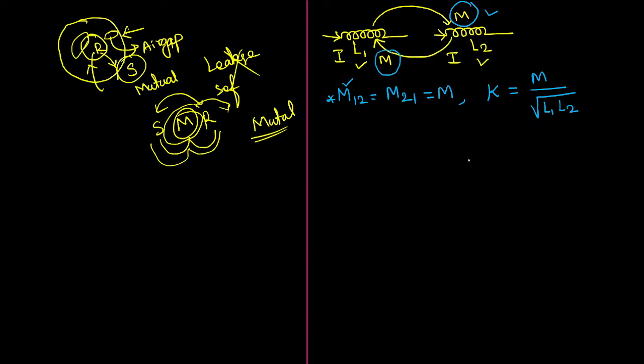The derivation is there; you might have gone through it in the lecture. This is in terms of electrical inductance. This came from the derivation. I have skipped that part here because we are in a revision session, and I cannot prove everything. So M will be k times the square root of L1 into L2. Suppose it is given that the coils are identical to each other.